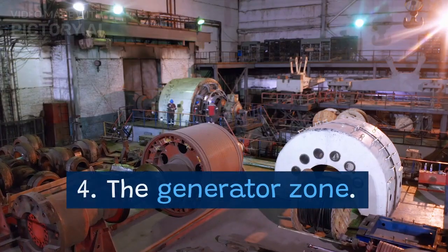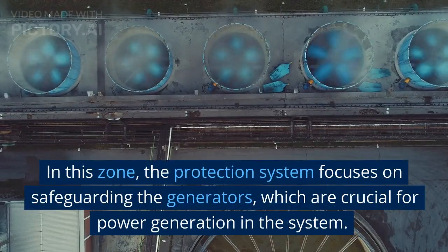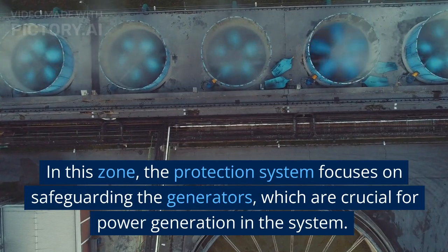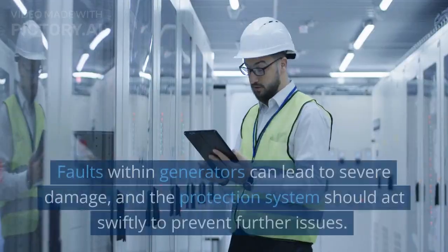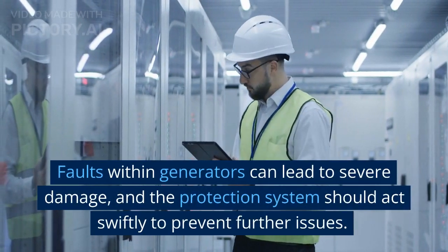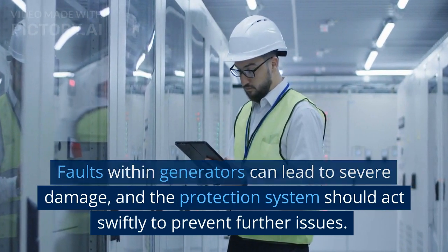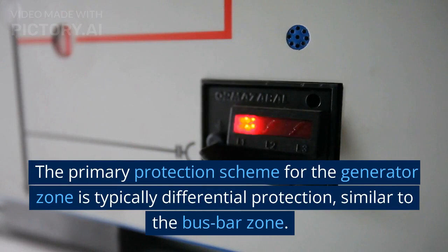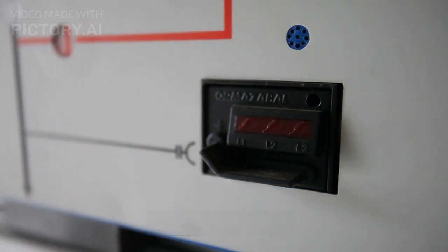Lastly, let's discuss the generator zone. In this zone, the protection system focuses on safeguarding the generators, which are crucial for power generation in the system. Faults within generators can lead to severe damage, and the protection system should act swiftly to prevent further issues. The primary protection scheme for the generator zone is typically differential protection, similar to the busbar zone.